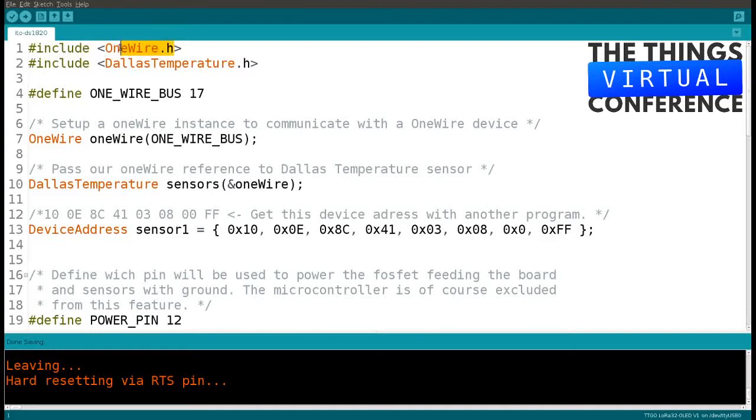And often in these .h files, you will find the possibility to do some settings. That could be IDs, in the case of BME 280, etc. And here we recognize this ID we found before. I already put it in here. It can be different. The 0x just tells the software this is a hexadecimal number.